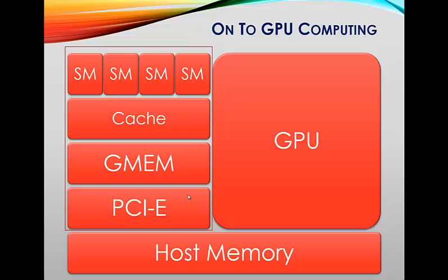As you notice here, each of those GPUs that you see on the right as a block diagram can be split into its component blocks: a bunch of streaming multiprocessors connected through a cache to your video RAM and through your PCIe switch to your host DRAM, or your CPU on the motherboard.